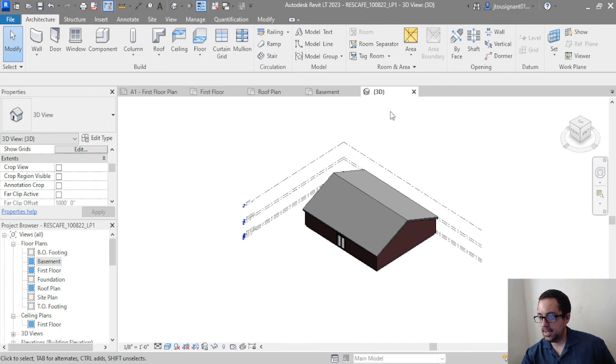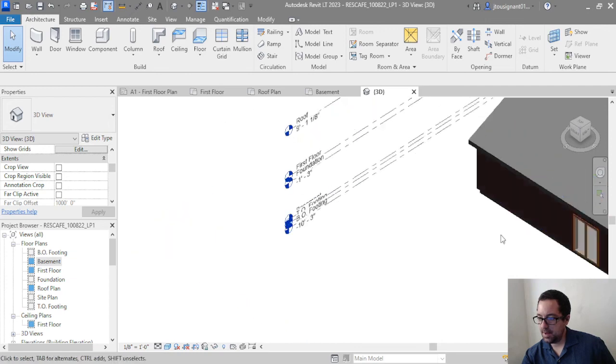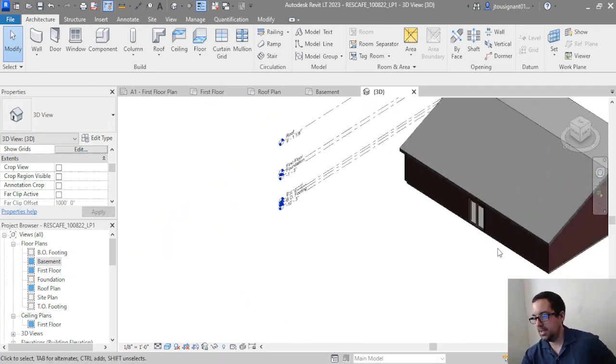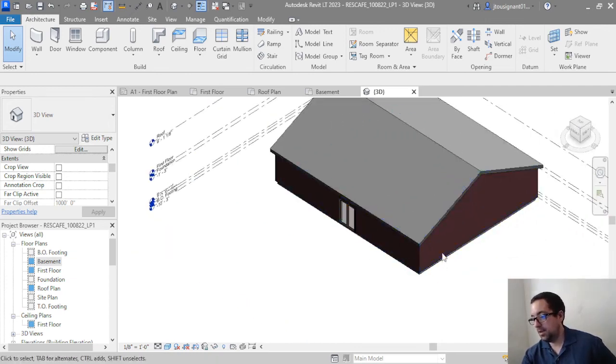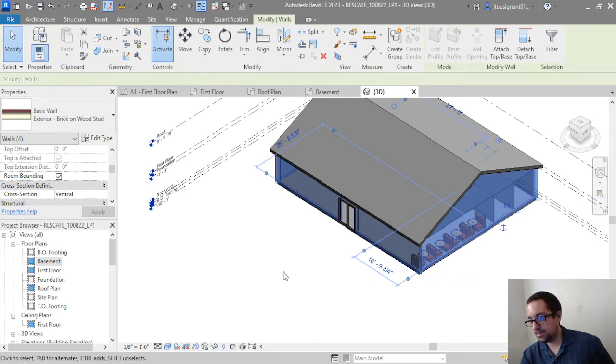So let's get into the basement. So we have a basement. Our exterior walls aren't going down to it, which is good because we're going to be usually housed by a foundation. And if we are still playing that this place is like a house or something that was turned into a cafe, it probably has a pretty standard concrete foundation or a step concrete foundation. So I'm just going to select all of the exterior walls and make a foundation with them.